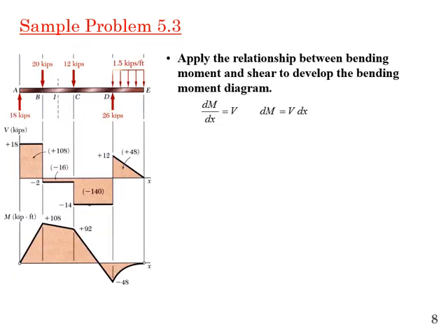Okay, now the bending moment will be equal to the area under the shear force curve. If you look at the area under this segment, that is equal to 18 multiplied by this distance, and this distance was 6 feet. So 18 multiplied by 6 is 108. Now the bending moment will always be one order higher. So it will be 0 at A, and it will change linearly from A to this point B, and the value at B will be 108 kilopound inch. Sorry, kilopound feet. We are taking it in feet.